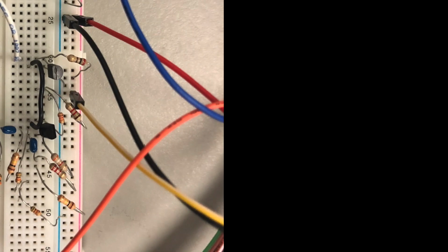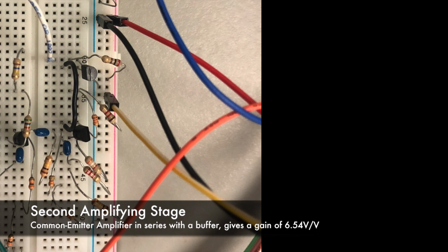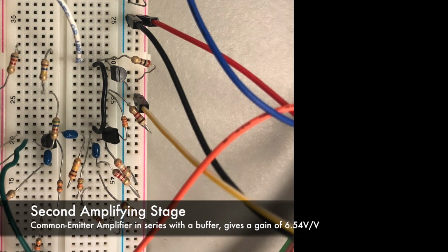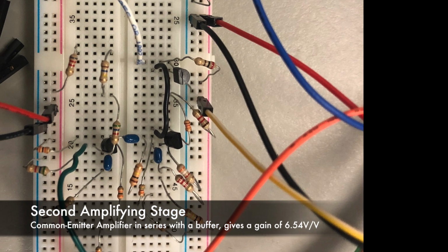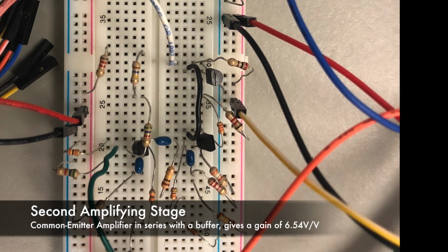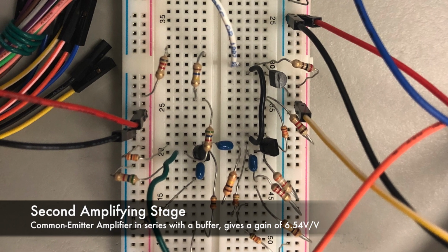For the second stage, we use a common emitter amplifier model in series with a buffer. We designed it to achieve a gain of 5. The load of the buffer is the input resistance of the power stage. We make sure the input resistance of this stage is large enough to enhance the connectivity of the circuit.